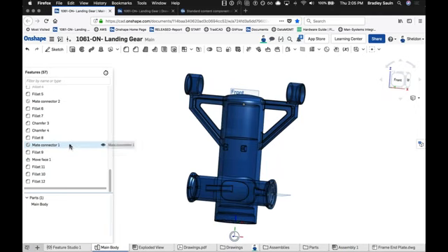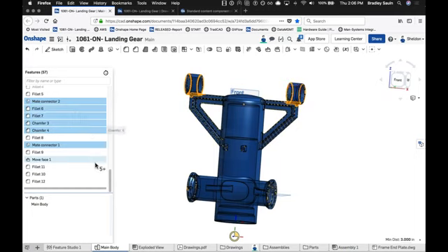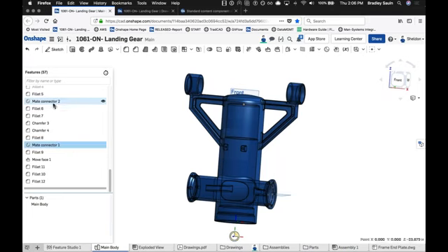Now with Onshape, I can actually select multiple features in the feature list. I'm just left clicking. Again, we have persistent selection, so you don't need to control click here. But of course, you can always shift select to get a full range of the features as well. But I just want to move these two make connectors together and at the very bottom of my feature tree now. So I can select them even though they're in different locations, and then click and drag down. And we'll notice I have an indicator that I have 2 items selected. And as I drag them to the bottom and release, both get moved down to the bottom together. I find that to be very powerful just to help reorganize your designs, especially if you're just cleaning things up or wanting to make things more easy to reference from a design intent standpoint.